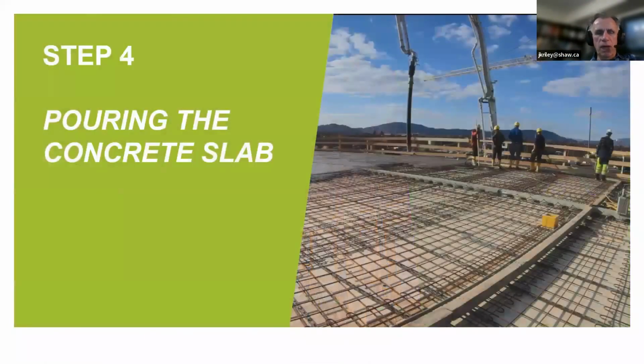On top here, what we're looking at is the concrete slab. And this is straight goods right out of the back of any pump truck, any mixer truck throughout North America. And you can see here the mesh and then rebar. The mesh is tying the concrete all together, of course, and the rebar ties the composite beams into the concrete. And then the concrete's pumped and poured in place. Now, the concrete, straight goods, about 4,500 PSI, 7-inch slump, 1/2-inch granular.